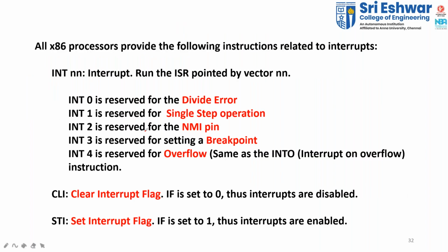And next, interrupts. Basically, in 8086 we can generate up to 256 interrupts. So 256 software interrupts can be generated, out of which these five interrupts are important: interrupt 0, 1, 2, 3, 4 are more important than the others. All these interrupts are software generated. I can program and name my interrupt as interrupt 25, interrupt 39, likewise. So these five interrupts are important in the 8086.